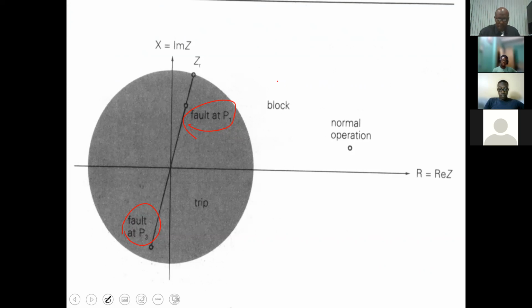relay looking in both directions. And once the impedance is less, West Kings House is then connected to Boulevard. Yep. So if the relay is at West Kings House and we are using these characteristics, it will be looking on the line towards Hope and it will be looking towards Boulevard. All right?